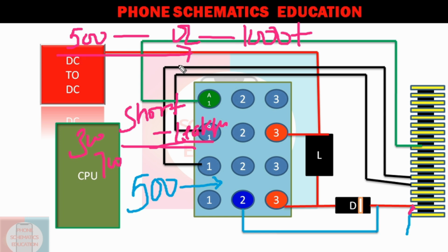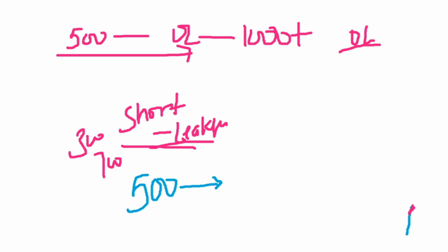Now, third scenario, if you did not get any value on a forward bias or reverse bias, you will see OL. Basically, I will tell you again. First, clear this thing. There are three types of scenario in diode mode testing or cold testing.